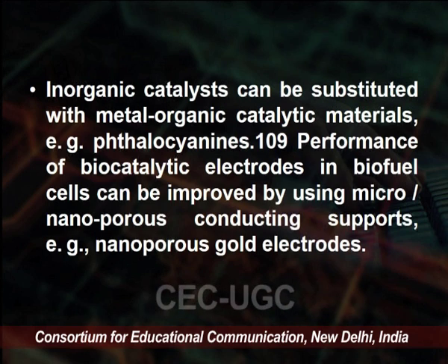So, biofuel cells are potentially useful for activating microelectronic devices in bioelectronic or microrobotic systems. The inorganic catalysts and active electrodes in the fuel cell can benefit from the use of nanostructured catalytic species. Inorganic catalysts can be substituted with metal-organic catalyst material.